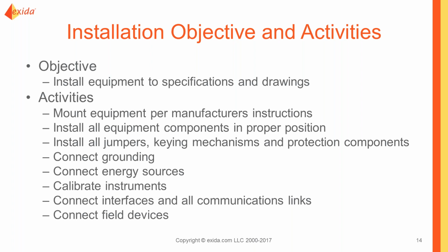Because then you've got that system in place, or often it includes the FAT, but it would include the steps such as confirming that the SIL verifications are correct, confirming that the different requirements are written out. FSA 3 is the assessment that occurs prior to startup. Must be done, all the equipment is installed, it's ready to go in an operational state, but the hazard isn't present yet. So that's, I think, a convenient one to think of.